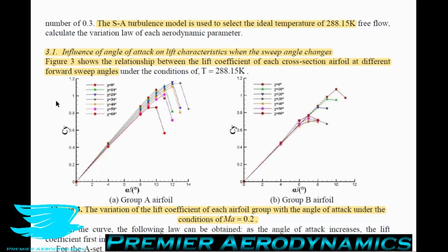So in other words, the stall angle is proportional to the thickness to chord ratio of the wing. And this makes sense because we can look at some limiting cases. For example, a flat plate, the stall angle is very low. It's like 2 degrees or so, and it sucks for producing lift past that. But if you go to a very thick airfoil, for example, a NACA 0020 or NACA 0030 perhaps, the stall angle dramatically increases. So this is what we're seeing here, so that makes sense.